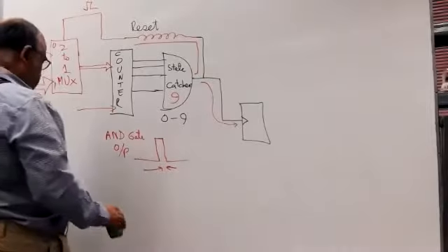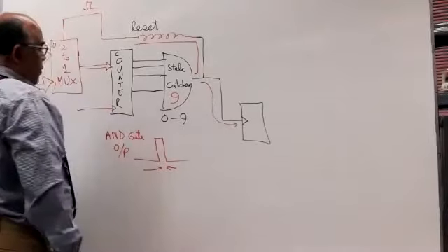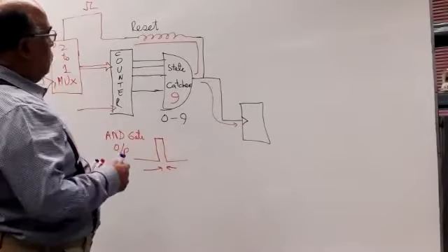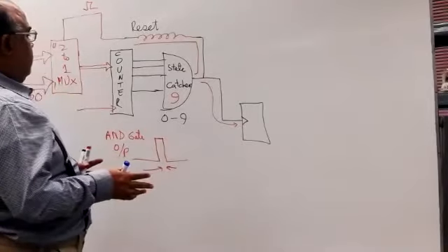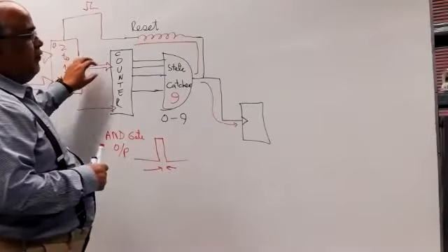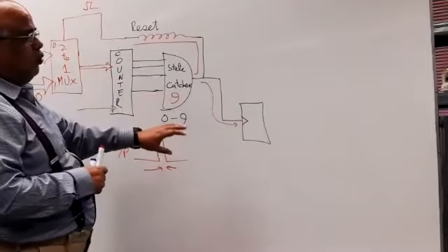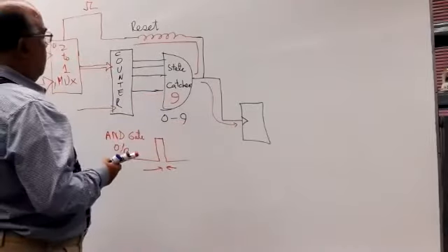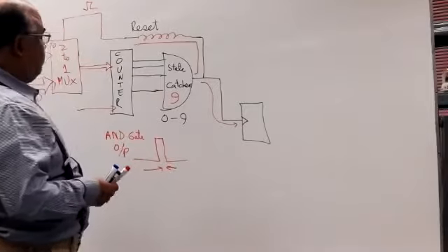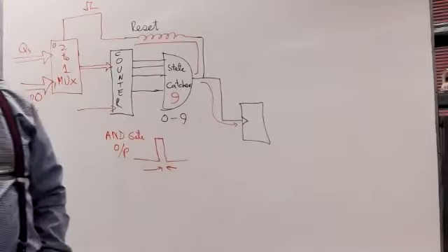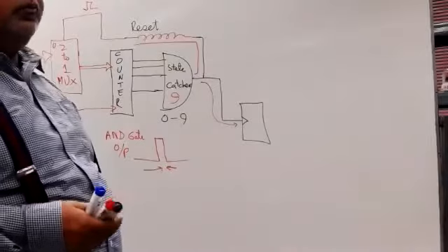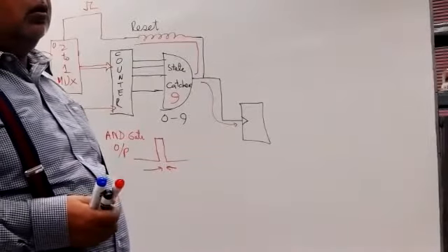Yes, good question, a very good question. Now see, if the situation is that you want all the counter outputs to change simultaneously, you don't want one D flip flop to clock another, and that to clock the third one, and that another one. That is usually not very much appreciated in circuits where you want everything to occur on a clock. So in processors, sir, or where is asynchronous appreciated then?